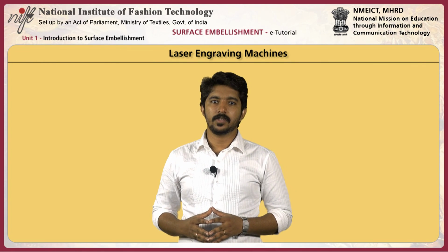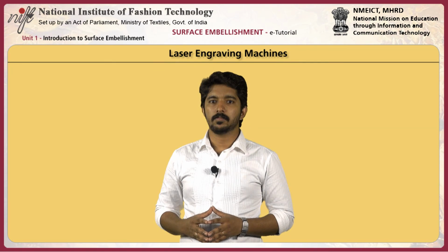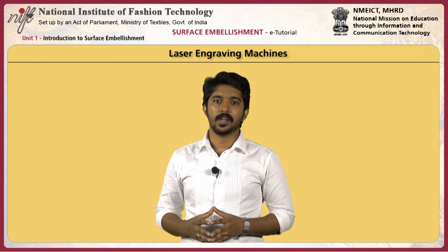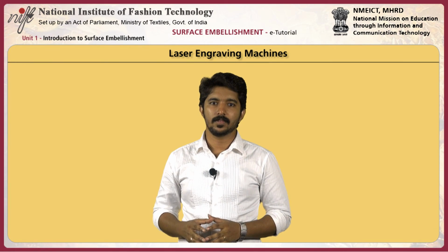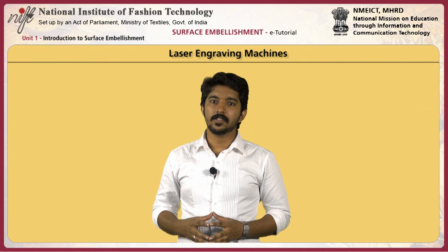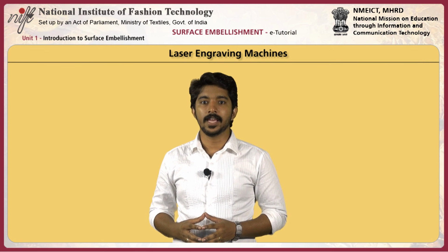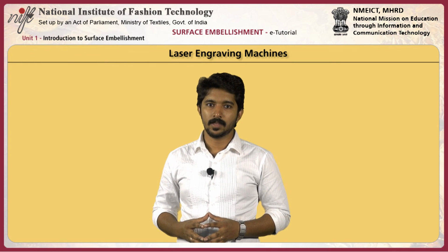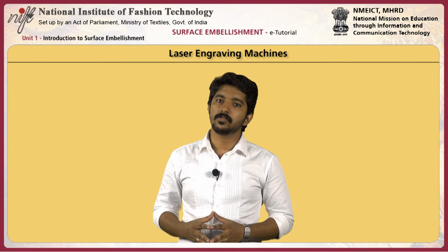The laser computerized engraving machine can engrave and precision cut in one process on a continuously moving bed to a maximum size of 1800 mm by 1800 mm with speeds up to 24 meters a second. This process can produce images, text, logos and textures on finished items or raw materials including leather, wood, plastic, man-made and natural fabrics. It can also be used to change the color and the texture of some surfaces.